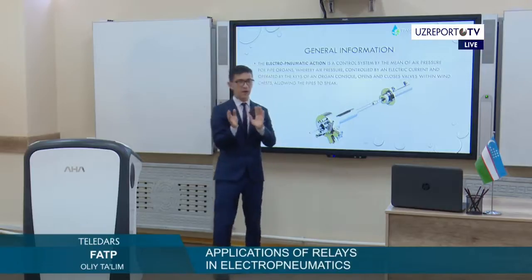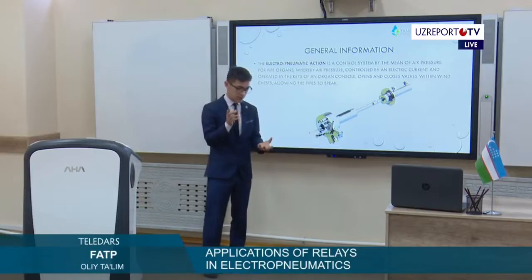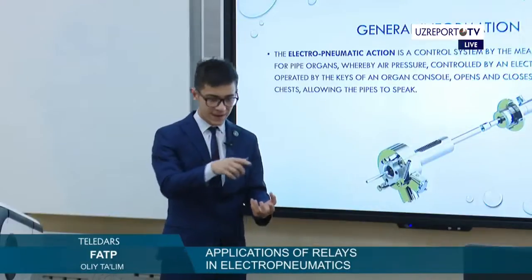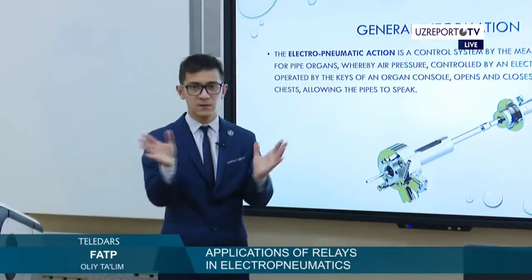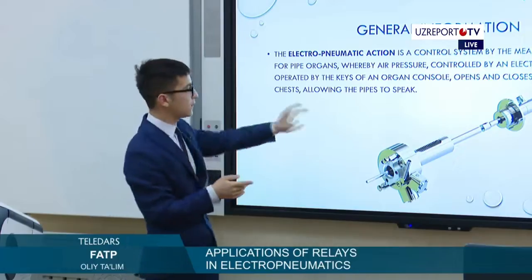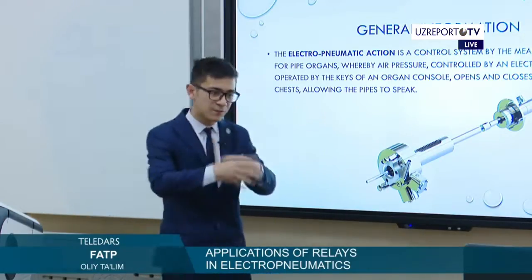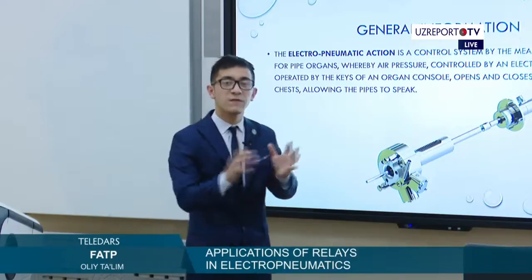These actions you can use for everything that needs pressure in air circulation. And I give you an example like the Coke company. Why? Because filling the bottle with Coke liquid and closing it is based on pressure work. So the Coke company uses these electropneumatic sets with relay contacts to make their process fast and effective.